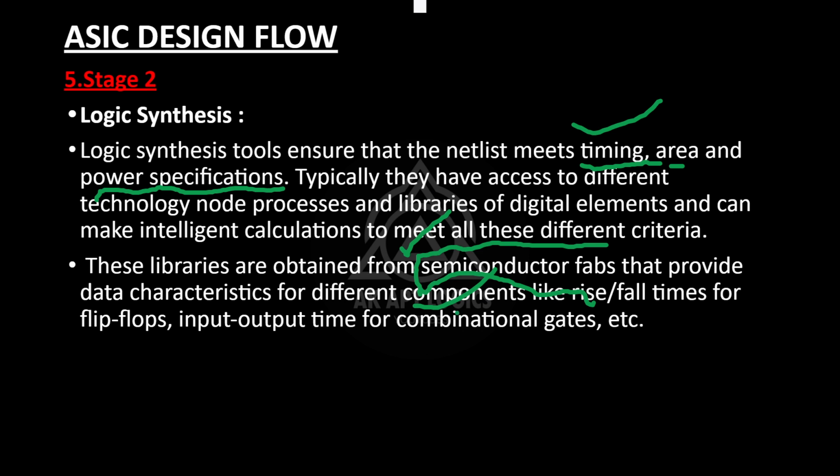Fabs in the sense here also product-based company. Fabs are those who will make the chip, who are going to make the chip physically. Those will be called fabs, in the sense fabrication industries. So all of this will be in those libraries: the rise and fall times for flip-flops, input and output time for combinational gates. All this stuff will be there.